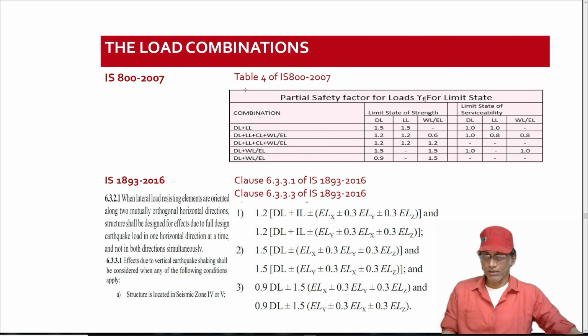In the last sections, we have learned to define the primary load cases, that is the gravity load cases, the seismic load cases and the wind load cases, and how to apply those primary loads to the STAAD Pro model. Now in this section, we will learn the load combinations, that is how to define the load combinations involving all the primary loads that will be acting on the structure and how to apply these load combinations in a STAAD Pro model.